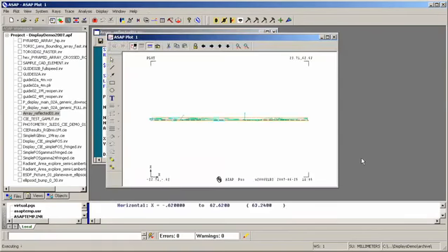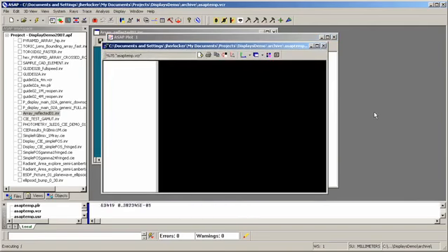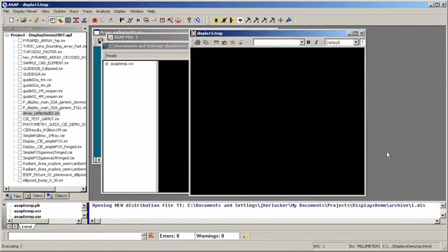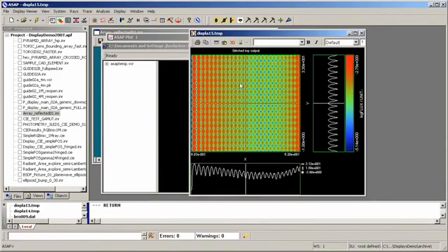You can't tell from this side view, but what I am looking at is one column of dots and one source in a display. And if both of those units repeat, then we can use mirror symmetry on the sides of those planes to model the effect of this system without having to model the whole system. In most real systems, this would be an imperfect assumption, but it's a good way to get a very rapid feedback on, for instance, a new dot geometry. As long as we use a lateral repeat unit, we get a result that we can actually consider.